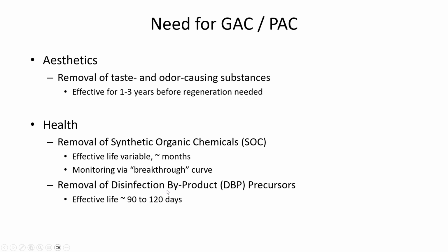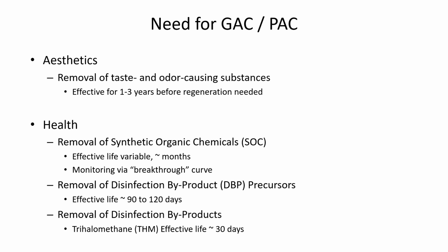And when you're using it for that, rather than just the aesthetic flavor improvements of water, then your activated carbon doesn't last quite as long. And it can be regenerated. They can take the activated carbon and heat it up, and that causes the organic chemicals that are sorbed onto the outside to become airborne. They volatilize and go into the atmosphere, and then you could reuse the carbon another time.